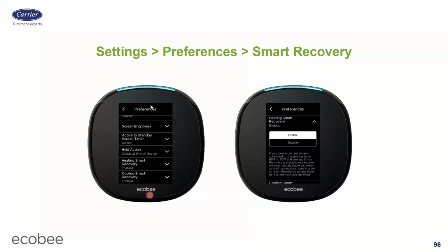So let's first decide what smart recovery does. Some manufacturers of thermostats will call this adaptive recovery, intelligent recovery, optimal start, whatever other weird names they have for it. What that means is those thermostats look at the previous day or the previous 3 days or the previous week or whatever it is, and they say, you know what, based on what's been going on, I think it's going to take this long to heat this house up or cool it down. So I know these folks want the house to be warm when they get home at 6 p.m., so I'm going to start at 5:17 today because I know that's going to take me probably about half an hour to get up to temperature, right? That's what this kind of feature does.